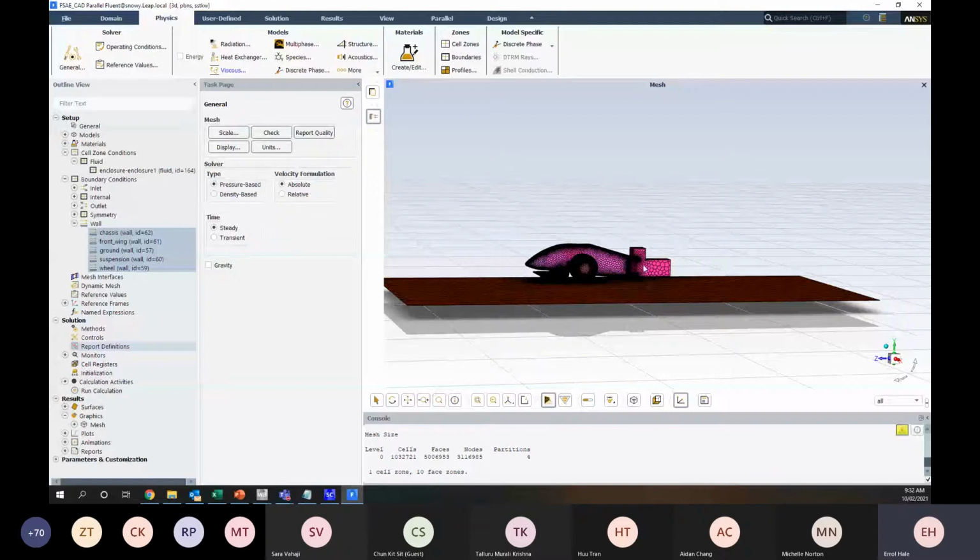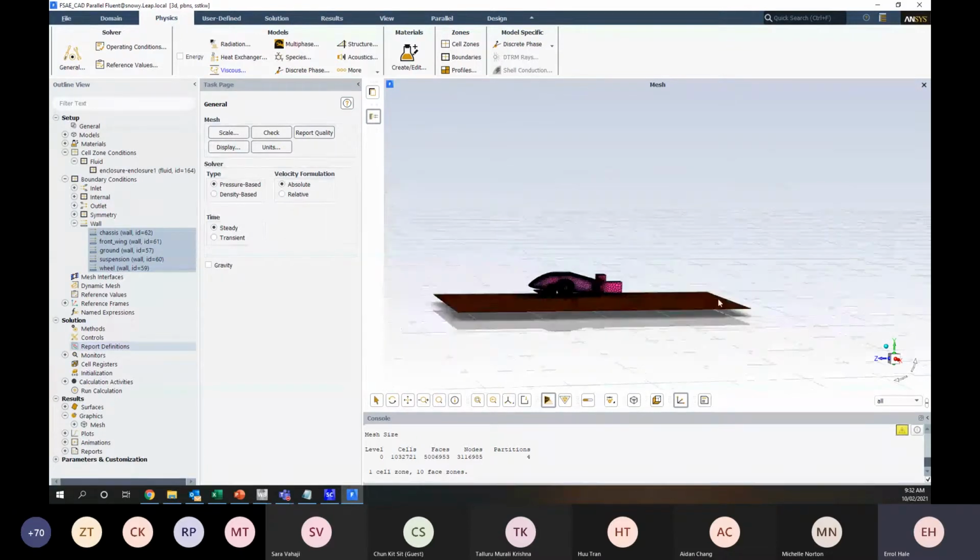If you run a simulation, you look at your post-processing and the flow field hasn't returned back to a steady, constant state before the outlet, then you need to go back to the mesher, go back to geometry, make it bigger, remesh, and bring it back in. Because one of the really interesting things about fluid dynamics is that what's going on behind here can really have a strong effect on what's happening up here. So if we're not capturing it in the solver, how do we know we're being accurate?